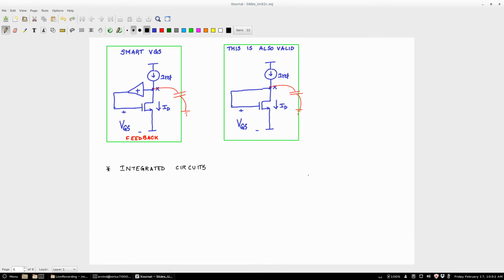Yes. So in an integrated circuit, you have multiple transistors made on the same wafer, and the temperature at one place will be roughly the same as at another place. And because all transistors were made in the same step, so how is a transistor made? Just take the substrate, then they deposit the oxide, then they make the source and drain, then they deposit the metal. But they do it for all the transistors at the same time, which means that if I want a nominal VT of 0.5 and one transistor has a VT of 0.45, then all transistors on that wafer will have a VT of 0.45.